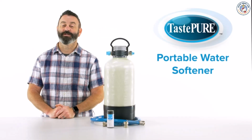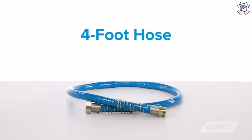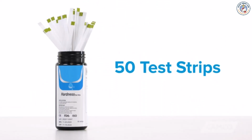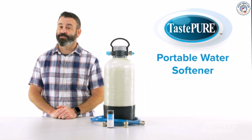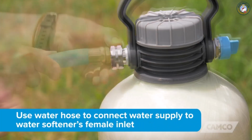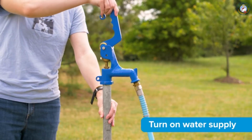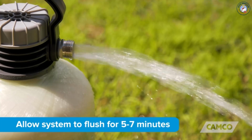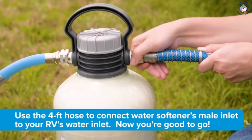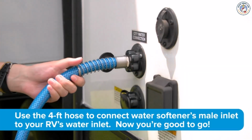This ready-to-use kit includes one portable water softener, one 4-foot hose, one male-to-male hose fitting, 2 storage caps, and 50 test strips. To install, turn off your water supply. Use a hose to connect the water supply to the water softener's female inlet. Turn on the water supply and allow the system to flush for 5 to 7 minutes. Turn off the water supply and use the 4-foot hose to connect the water softener's male inlet to your RV's water inlet. Now you're good to go.